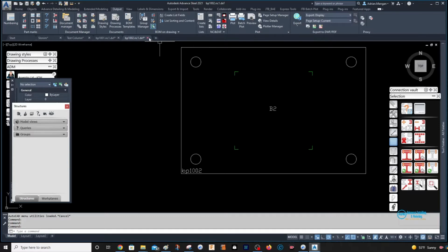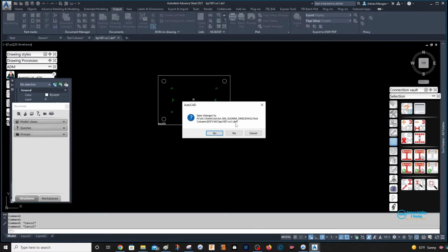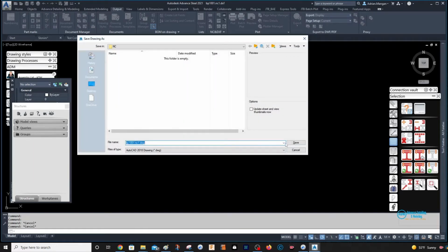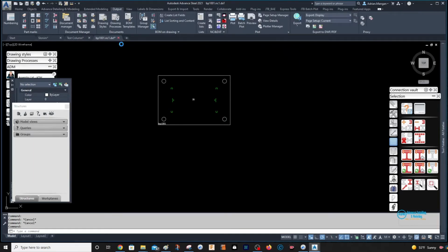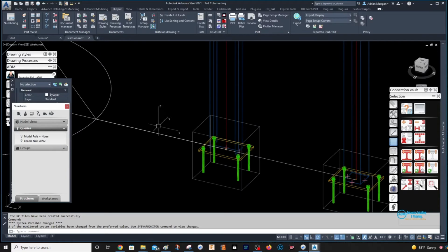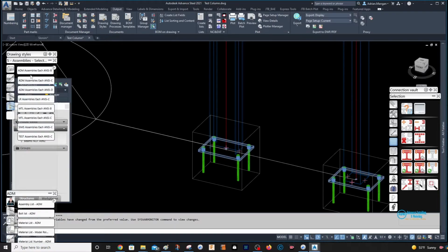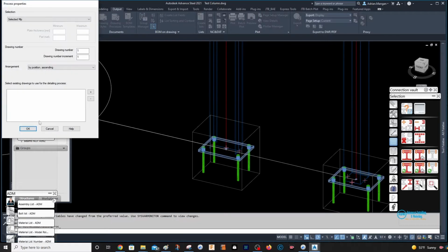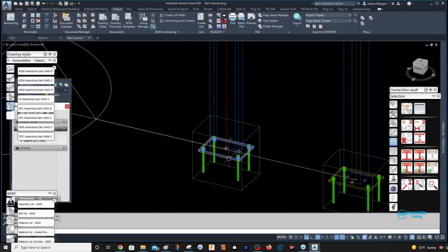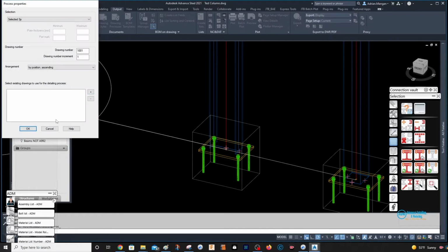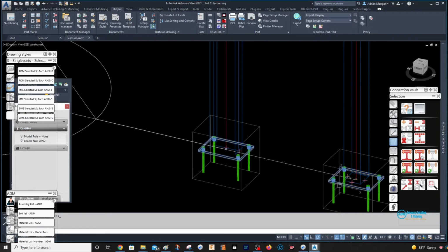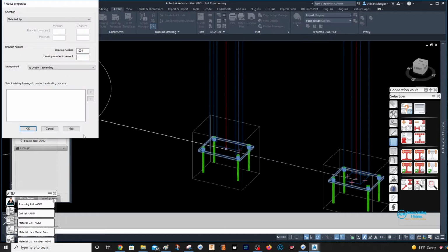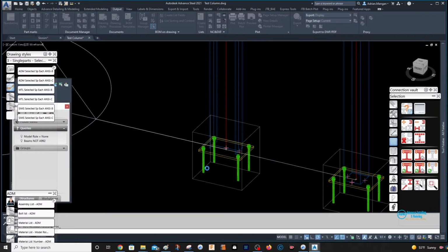So now the other thing I want to do is we can do scribing on these, or punch marks. So what happens is if I do piece detail, so if I do the 2 piece details for this, so select these 2, and let's put them on drawings. Oh, sorry, I picked assemblies by accident. So I'll put these 2 on drawings.